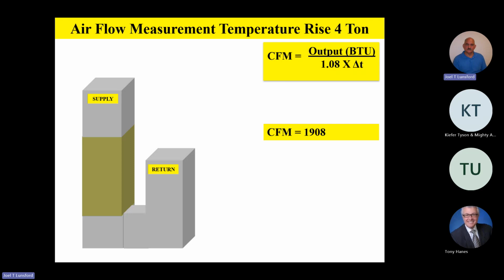And the point I'm making with this temperature rise method, by the way, fellas, is you can use this any time of the year. It doesn't have to be in the wintertime. You can energize the heat strip in the summertime if you need to, just quickly, for just a few minutes, to take an airflow measurement on whatever selected speed tap that you have. Just remember, you're going to have the outdoor unit off, and you're going to energize the heat strip, and then you're going to select whatever speed tap you're testing, and you're going to find the airflow.